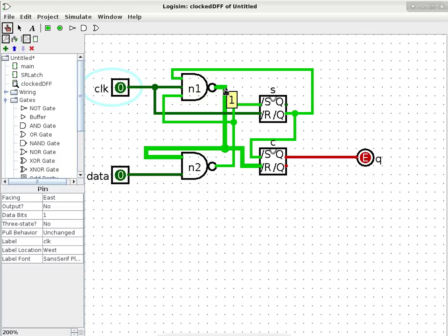Okay, but it also has a potential impact on the CSR latch. Because in this case, you can see how the output of N1 is going to the /R of the CSR latch, which means the CSR latch is going to reset, which also means the Q pin is going to be a 0. So we change the state of the actual memory SR latch, which is the CSR latch, to a 0.